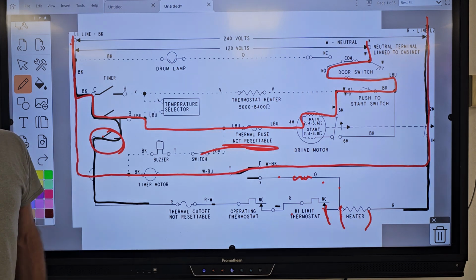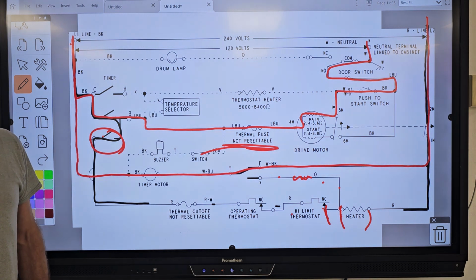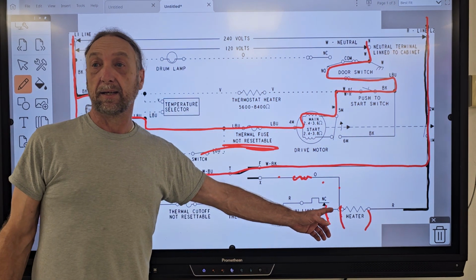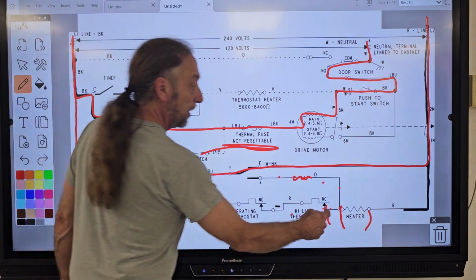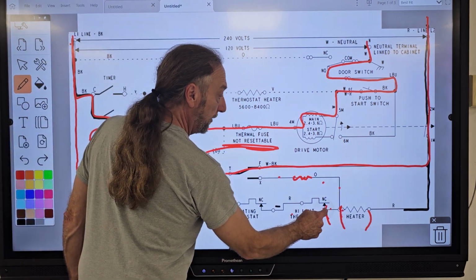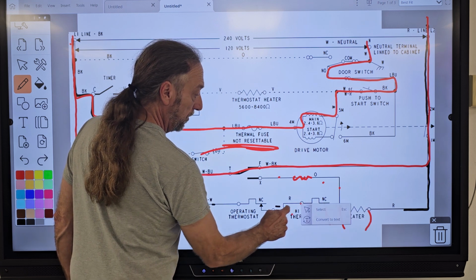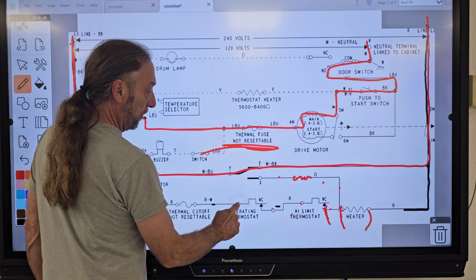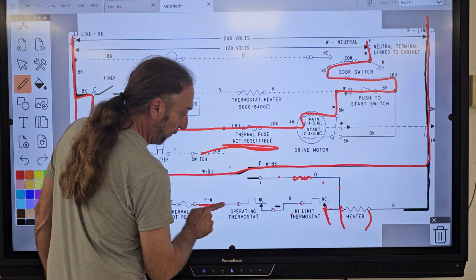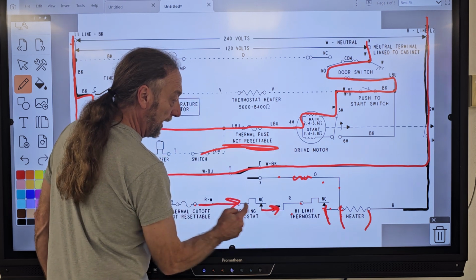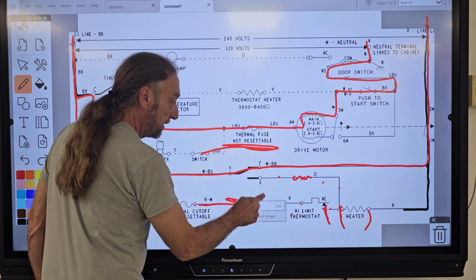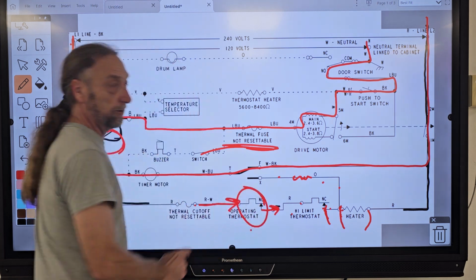If you have voltage there and you don't have voltage there, then the wiring between them is the problem. There's nothing wrong with... Exactly. And this is why we want to go load, wire, control, wire, control, wire. So this is voltage coming in, this is voltage going out. If I don't have it going out, but I have it going in, the problem is here.